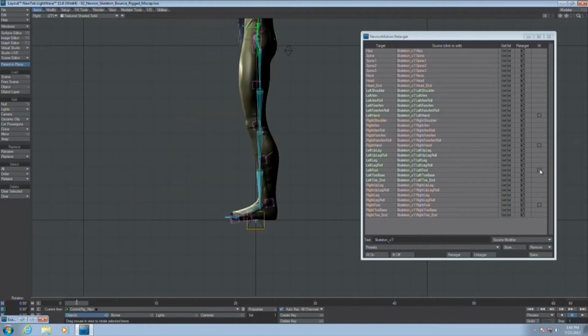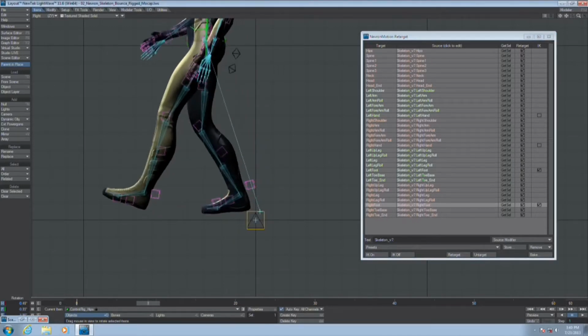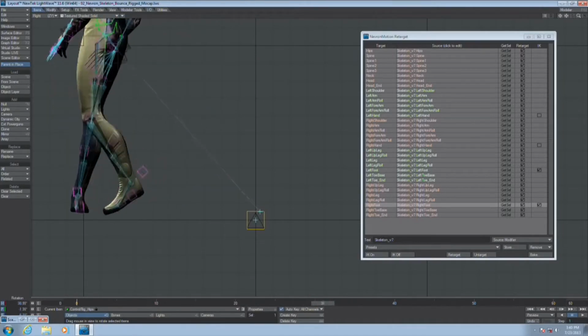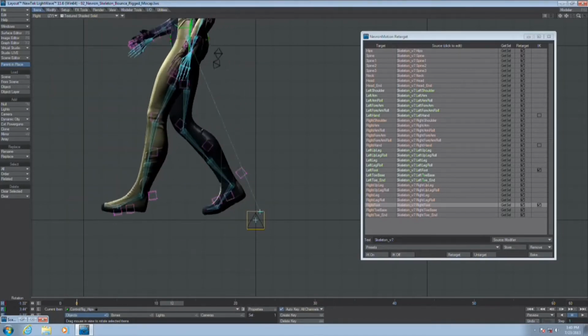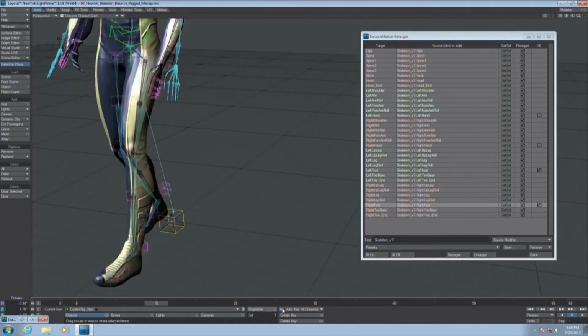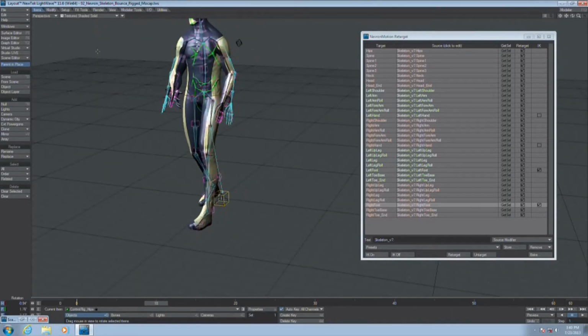So to do this, all we have to do is activate the IK solver for the left and right foot. So now I'm going to retarget again. And now the feet match perfectly. They are using the IK. Yeah, and the legs are following the IK solution then. So now we don't have the sliding problem anymore. Well, that was very easy. In the scene, yeah.